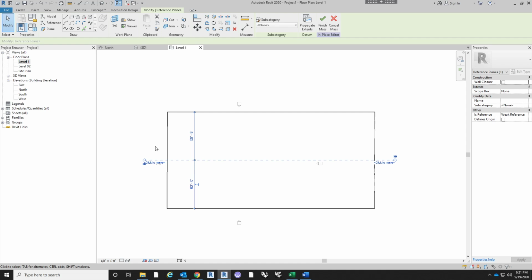If you do not name it, it will not show up in the next couple steps in a drop down of the plane. So you need to name your plane if you want to utilize it as a reference point for drawing two-dimensional shapes.